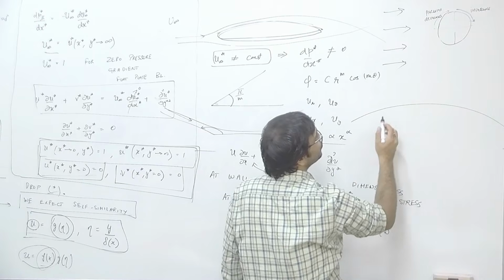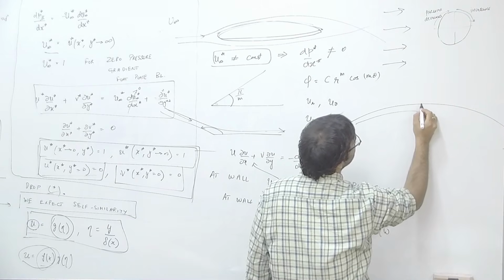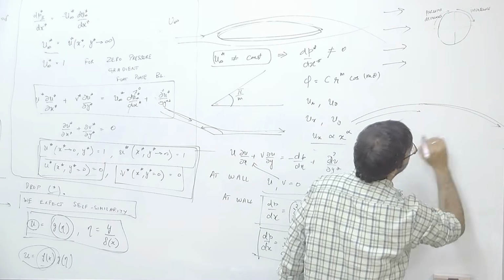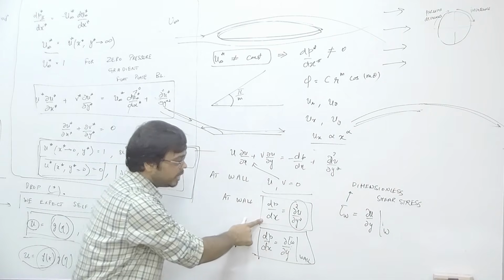And for many curved faces, this is exactly how it behaves: as you move further downstream till your apex, the pressure decreases and then the pressure starts to increase. So, when your pressure is decreasing, dp by dx is what?